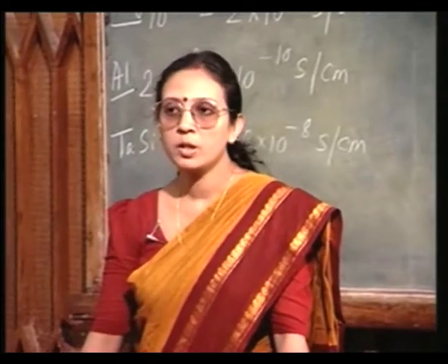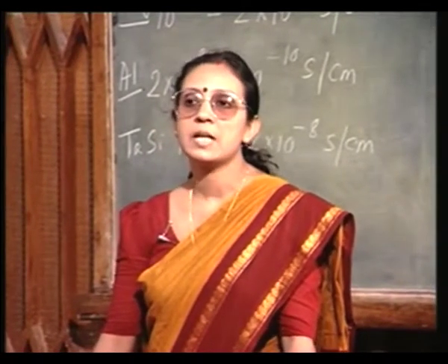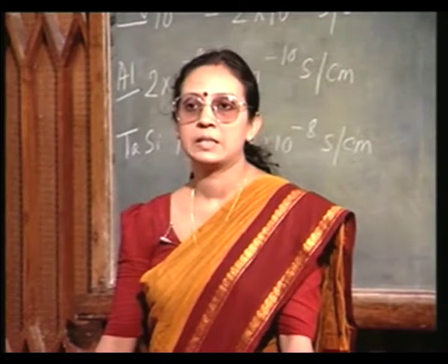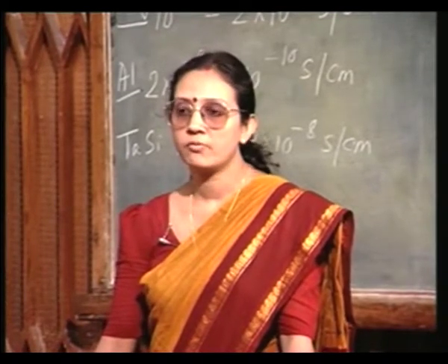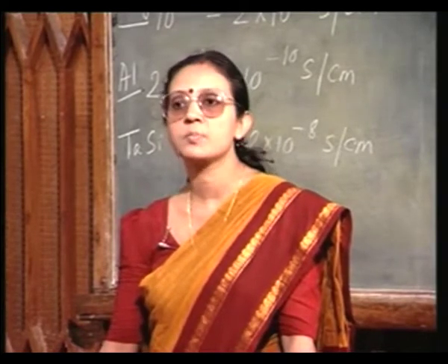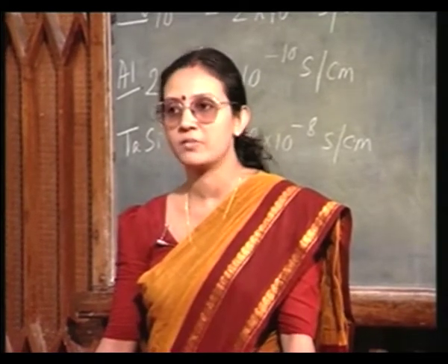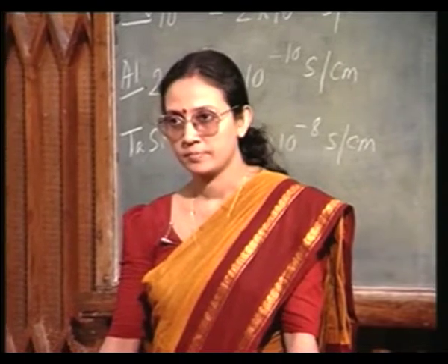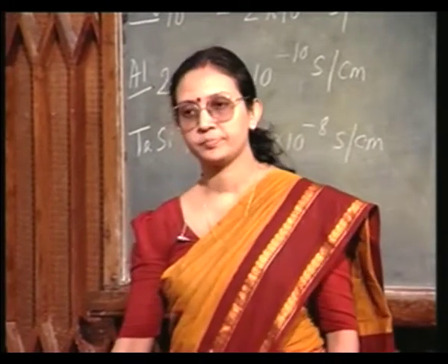The only problem with titanium silicide is that the reflectivity is bad. It does not reflect very well. So, any subsequent photolithography steps becomes difficult, because you can't see it very well. That is the only problem.